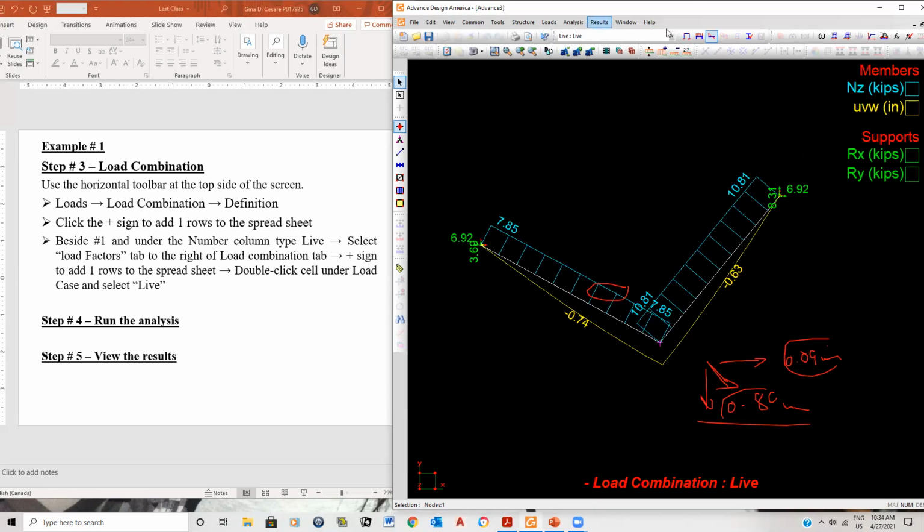Okay, so like I said, if you need to design cables, what I like about the program is that if ever you use cables as bracing in your frame, because it's a cable, it will never be able to take a compression force and it will totally disregard it in the analysis. That's how powerful this program is.